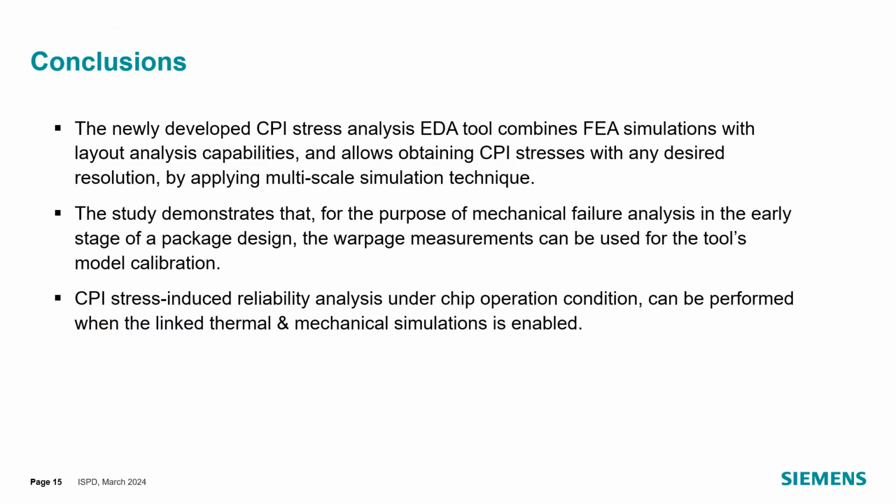In conclusion, we presented our multi-scale simulation methodology for analyzing CPI stresses. For mechanical failure analysis, we demonstrate that the warpage measurements can be used for the tool's calibration. We also presented the tool's capability of analyzing CPI stress-induced reliability issues under chip operation condition when the link between thermal and mechanical simulations is provided.